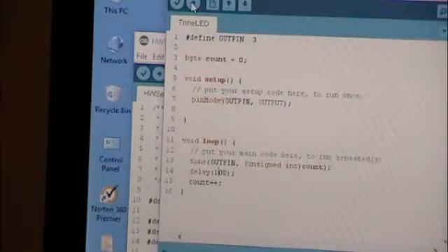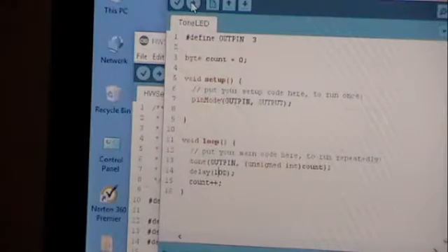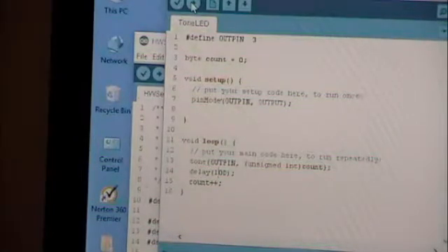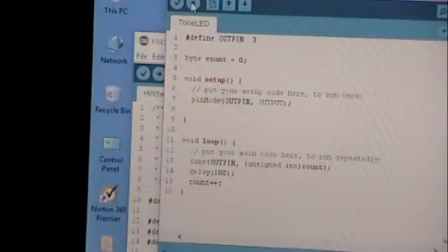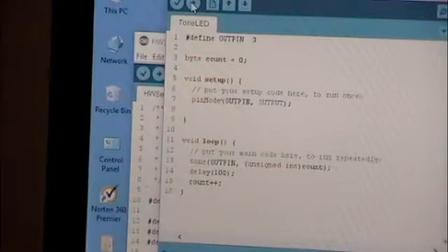You can read up on tone. The reason you can only do it on these pins with the tildes is because they are the ones attached to the hardware timers, and I will talk about those a skosh tonight. We've been an hour, I've got enough time, I think. What it's giving you is a 50% duty cycle square wave at the frequency you tell it. And there's a minimum and a maximum frequency, and I don't remember what they are.